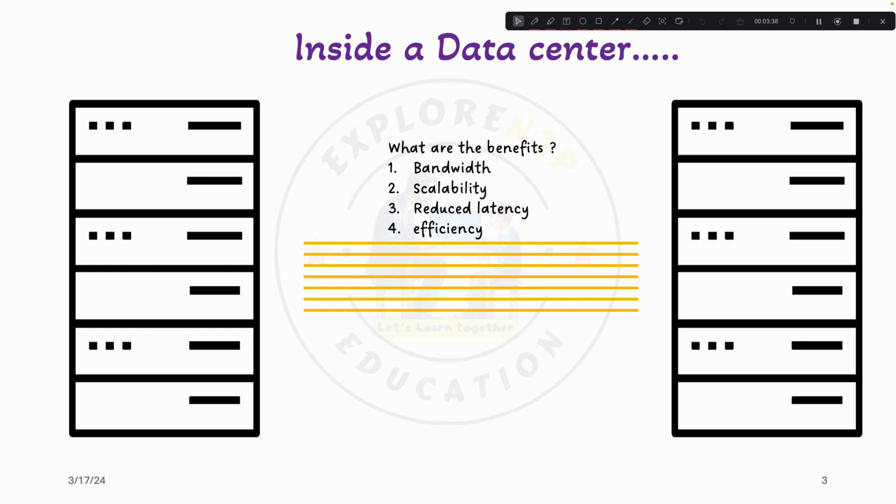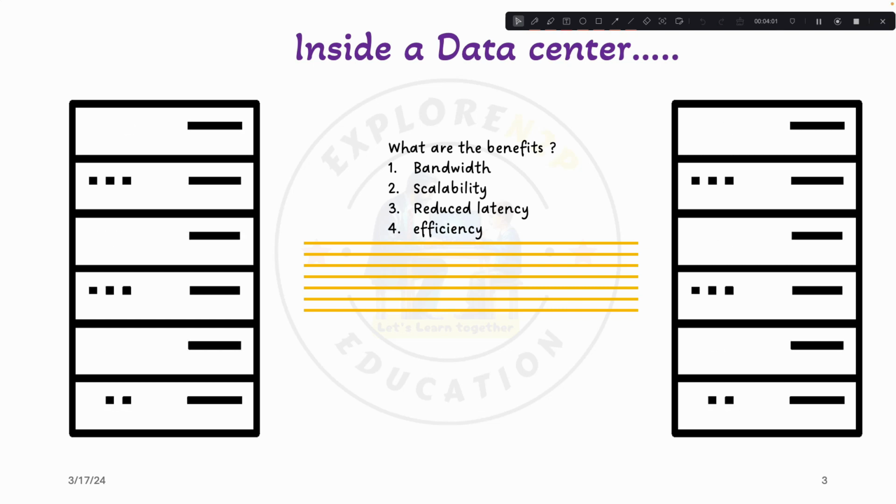The fourth one is efficiency. Efficiency here is about how much power is required to send a bit. When you are using single mode fibers, if you want to transfer high speed or high bandwidth data, then you need to use higher modulation schemes and high laser powers. It also requires a lot of complex electric circuits.